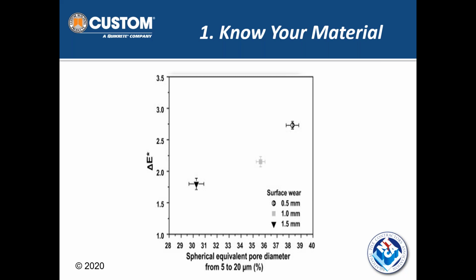What they're showing you is the more stock of tile that's removed during the polishing process, the less potential it has for staining. Simply put, it's because when you polish a porcelain tile, you are opening the body of it. And right at the surface, when it vitrified going through the firing in the kiln, there's air pockets and gas bubbles that are trapped right under the surface when it fully vitrifies. So if you remove more stock, you're removing all of those little pinholes that got trapped just underneath the surface.